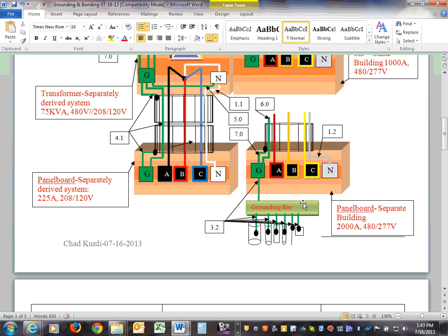At minimum, you have to have one grounding electrode system, typically the steel of the building or concrete-encased rebars in the foundations. If it's a concrete building that has rebars, that's good enough. One is good enough. As engineers, though, we never go with just one. You always drive a couple of ground rods. The code says minimum.